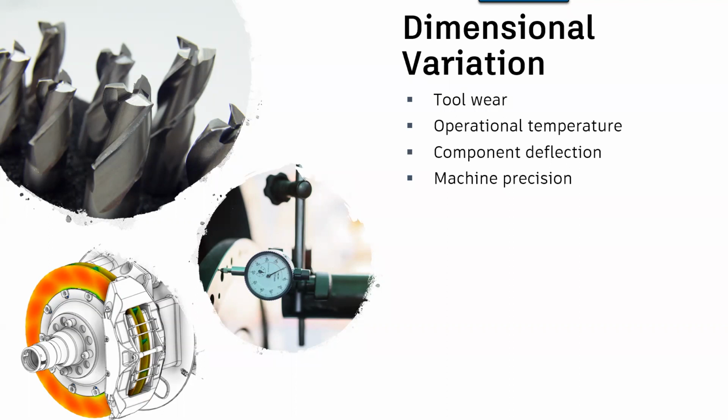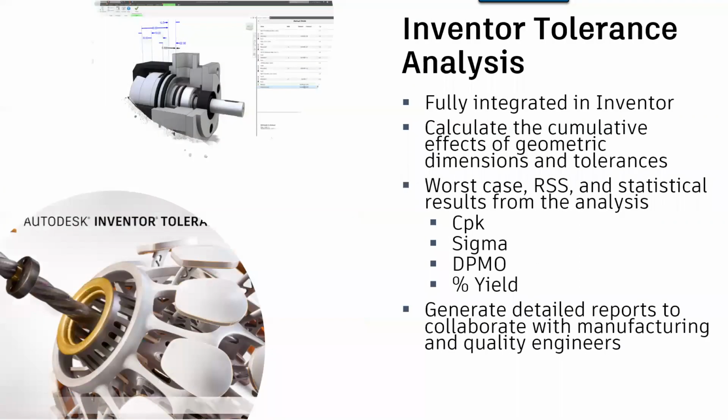If you're going to grind a part, maybe you really want to make sure that you get the surface finish to a specific measurement. Maybe the tolerance also has to be a little tight there. That's going to just drive up the cost. Is that really necessary, right? So what we're here to do today is to really analyze where we can analyze some of the trade-offs. Where can we maybe make the tolerance a little bit more coarse? Where do we need to tighten it up?